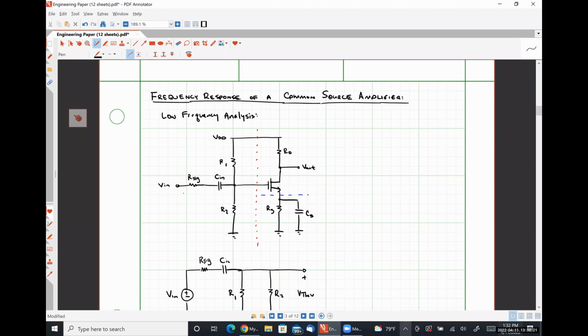Everything being multiplied by that is what's going to tell us how it behaves as a function of frequency. So it's very important that we are able to pull out the mid-band gain and then multiply that mid-band gain by a frequency-dependent function, because this has to settle to the mid-band gain as the quantity S, our frequency, gets large, or as we approach the mid-band region.